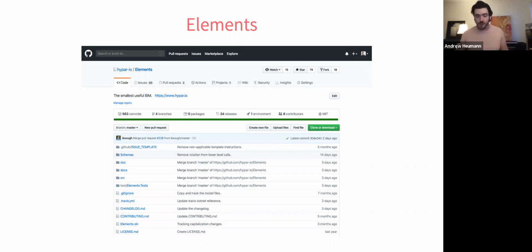For the representational piece, we also looked at systems like IFC, which are great. IFC is amazing. It's this incredible standard for representing building elements in an interoperable way, but it's not lightweight and it's very hard to extend, and support for it is incomplete in even the biggest applications like Revit. The number of times I've heard, oh, this IFC element didn't translate correctly when I pulled it into Revit. This is reality, and making changes to that is often out of the hands of even competent developers working locally.